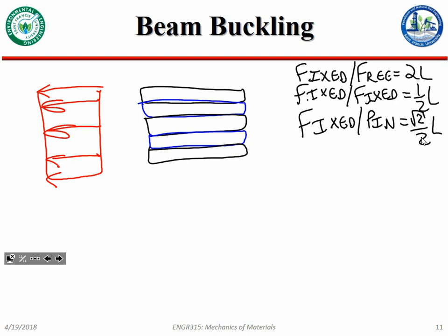The stress inside the material is going to distribute itself according to the stiffness of the different layers. So you'll end up with lots of stress here and just a little bit of stress here, which actually makes shear stresses a problem, right?